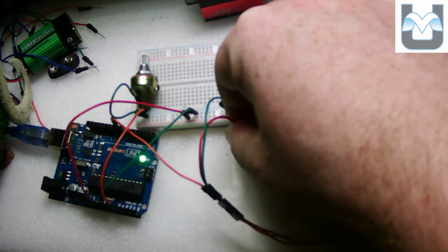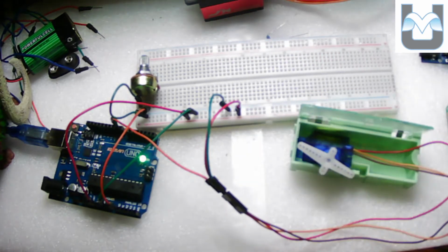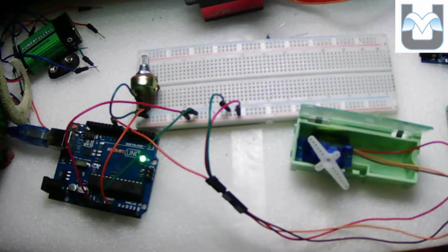Oop, and I've unplugged my servo. So I'm very quickly just going to plug my servo in. Now that servo is hooked up exactly like the Tinkercad circuit. I've got a wire running into the positive power rail, a wire running to the negative power rail. That's red and black, or red and brown respectively. And my orange wire, this one right here, is running back to pin number 9. You can see that servo works exactly like it does in Tinkercad. Okay, it's going just short of 180 degrees one way and the other.